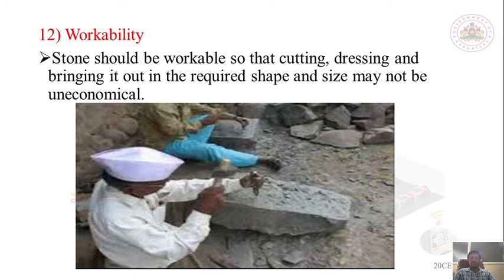So workability is nothing but the stone should be workable, so that cutting, dressing, and bringing it to the required shape and size may not be uneconomical. When you choose a stone, you need to be aware that cutting it and making it to the desired shape and size should not cost you more than the stone cost. Then that stone is not workable. So you have to choose a proper stone which has good strength, good durability, good workability, where you can easily place it, easily dress it, and easily make the desired shape. So that is a workable stone.